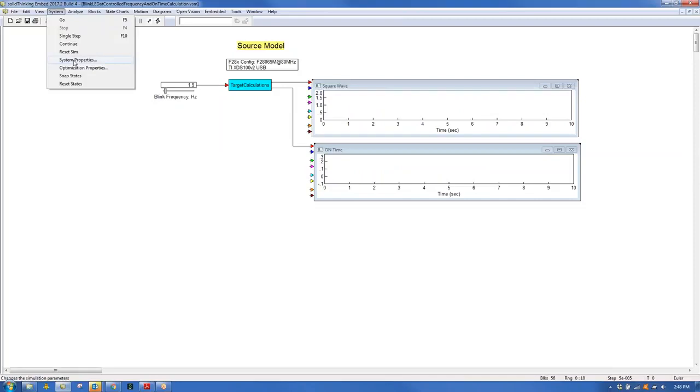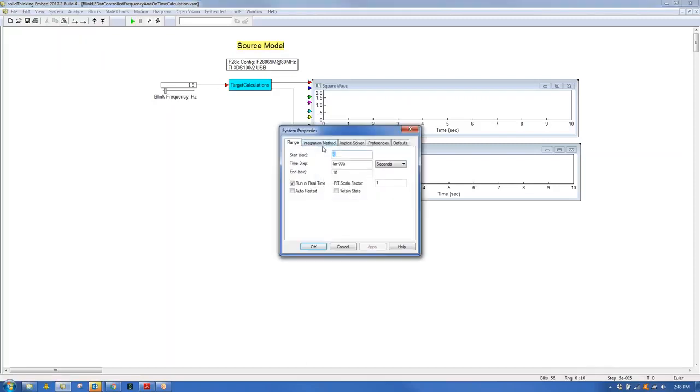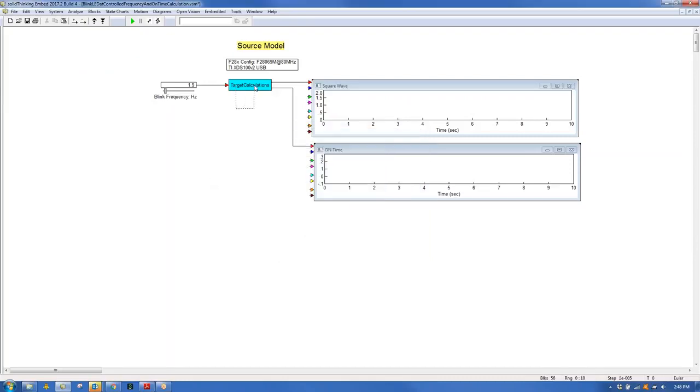Well, they're going to be identical up to a certain point, because what happens is the JTAG interface will only transmit data at about 200 hertz. So you will lose some data in that interface, and I'm going to talk about how to overcome that shortly, but just plotting it out like I have it, you will lose some data.